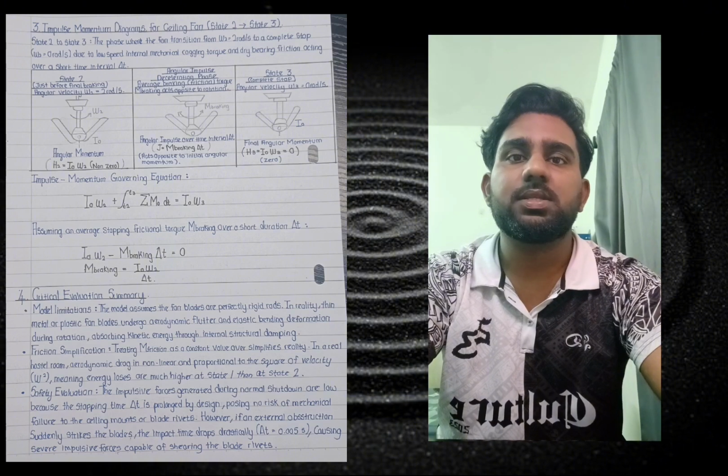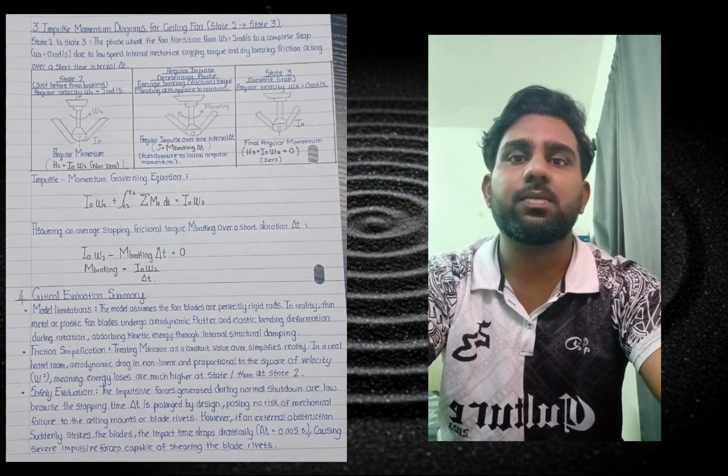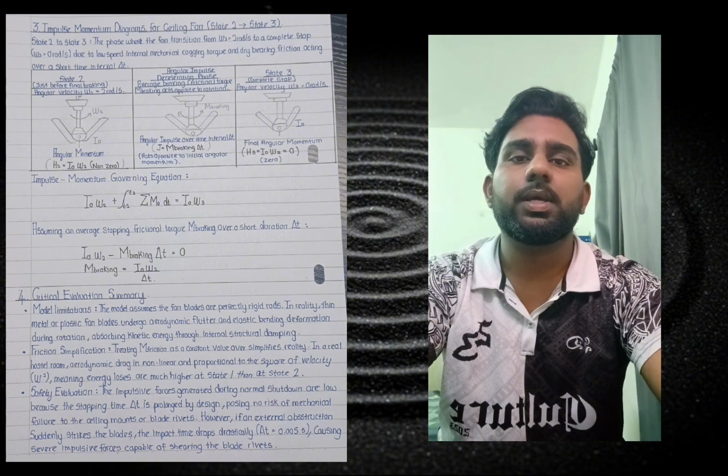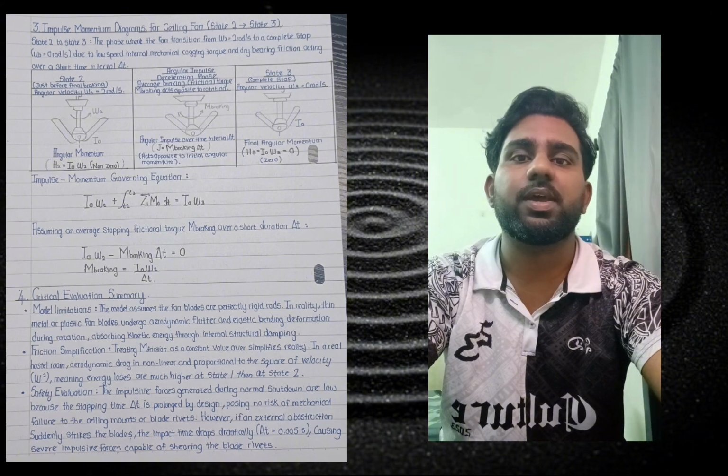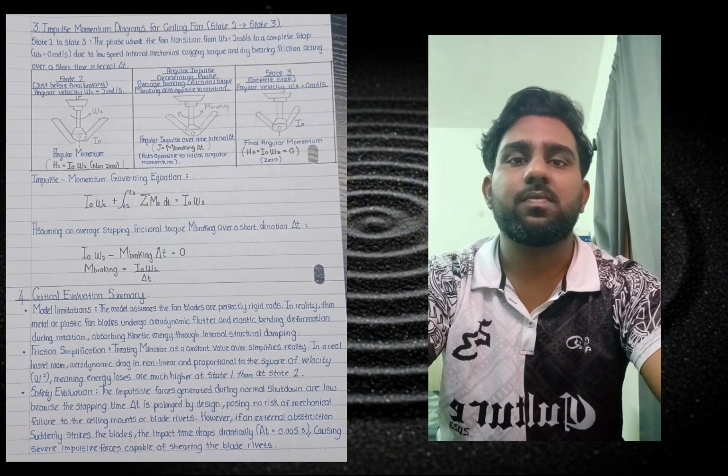To optimize this system, I propose a design modification: implement an aerodynamic blade profile with a variable pitch angle, reducing the blade pitch automatically when power is cut. This minimizes aerodynamic drag during coast down, reducing stress on the joint and allowing the fan to harvest its own kinetic energy smoothly if paired with a generator.